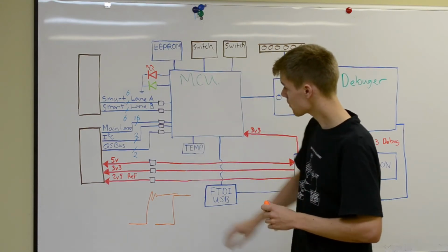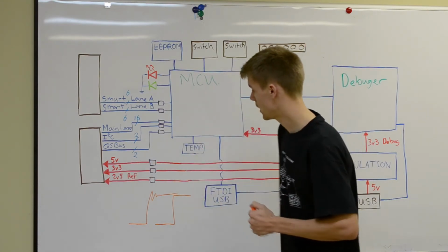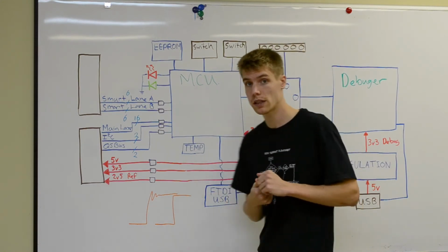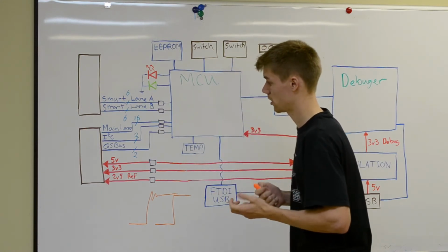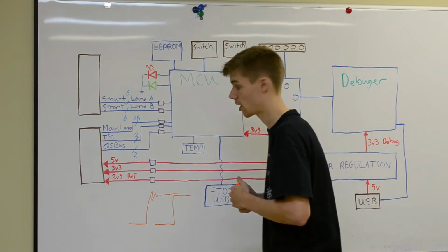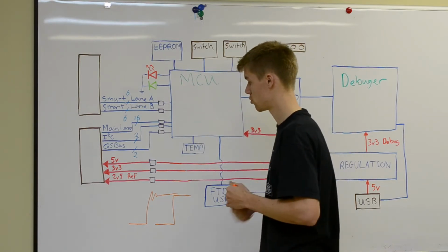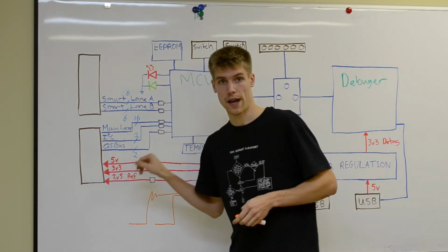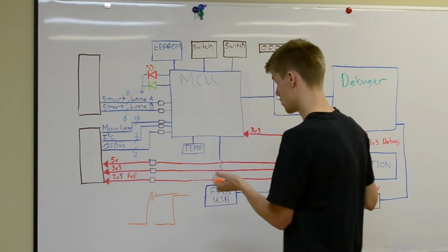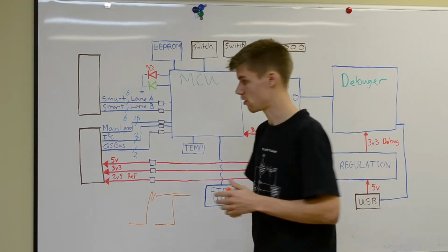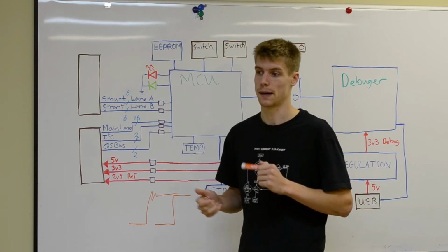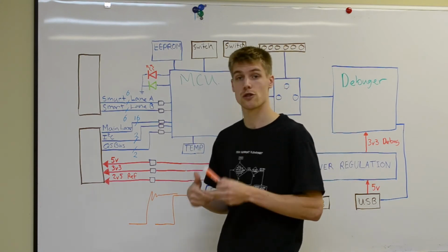The 5 volt line output has a current limit on it. That current limit is set at around 1.5 amps, which is really the maximum that the board is rated for in traces and so forth. When you go over 1.5 amps, a current source kicks in.